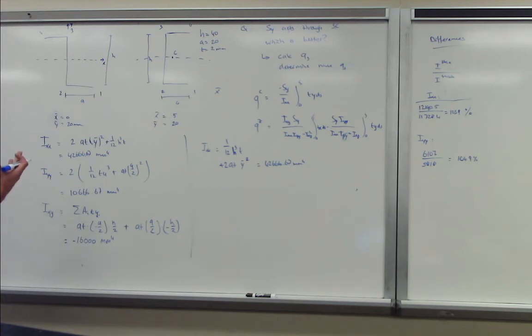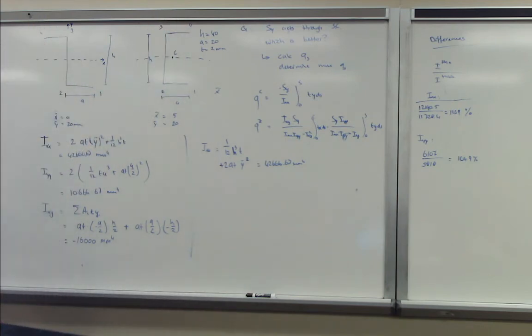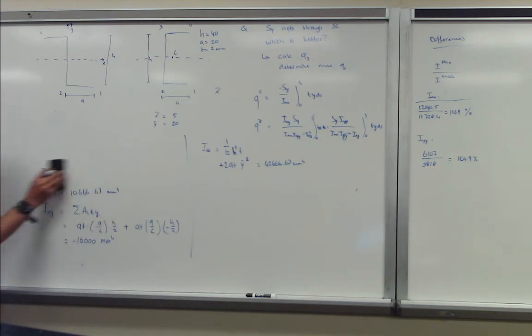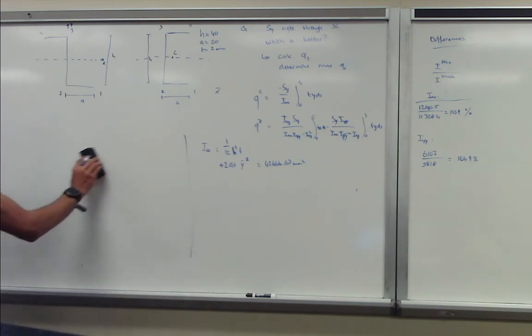Again, based on the geometries, we can assume that these two are equal on opposite sides, so we can ignore one of the calculation steps. We also know that the shear flow is maximum at the centroid, so first we want to come up with the equation for 2, 3, and then evaluate at the centroidal axis. Once we did this, we go into the calculation step for the shear flows.